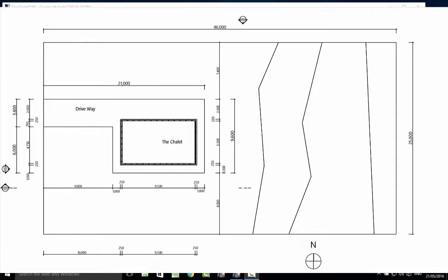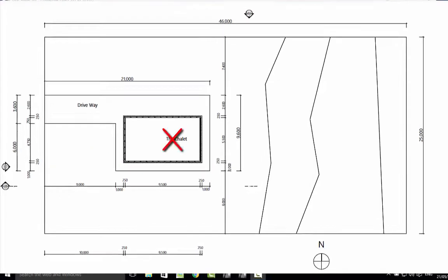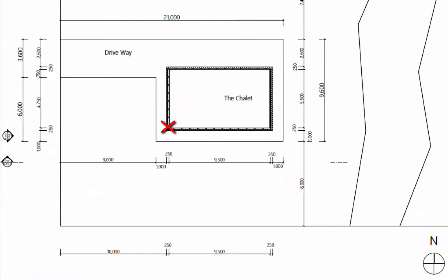And now we have to have a look at the position where we're going to start the walls of this house. If we look from the boundary line up to this wall here, we look across to the side and we see there's 8 meters and 1 meter, which is 9 meters. So from the edge it's 9 meters. From the front we can see down here it's 10 meters. Those lines coming up to the front wall. So this first corner, 10 by 9. Let's go and set the wall up.